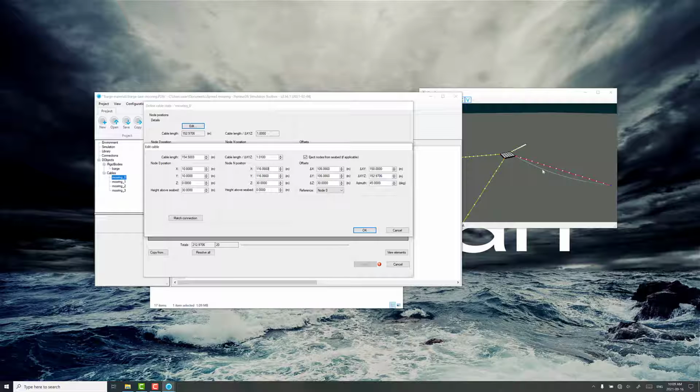And notice there's this little bit of sag here now. If you play with this number, you can see it's visually, this is very qualitative, it's very slack. But this is a lot better than this is fully taut. The pretension is going to be way too high. But something like this, 1.01, looks about right as a starting point. And we're going to show you later how to fine-tune this to the pretension you actually want. So we'll go, okay, so this is the geometry.